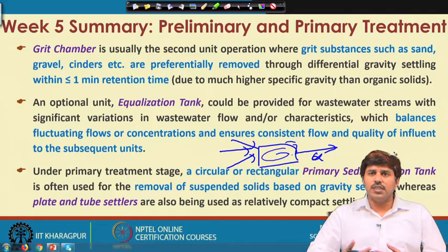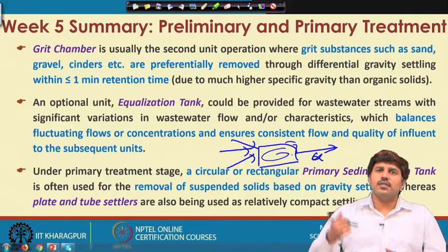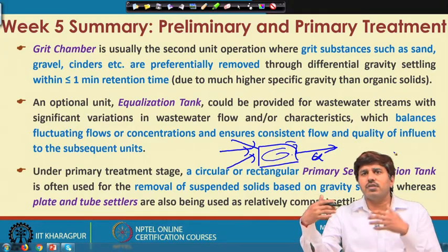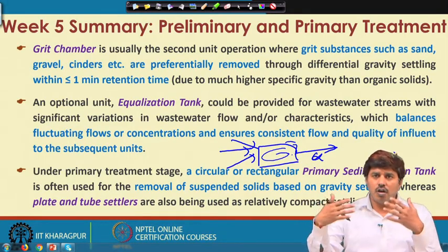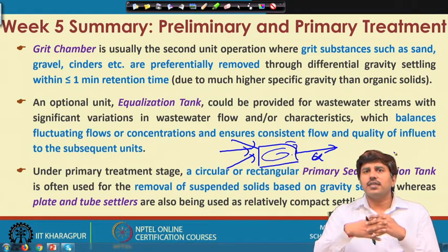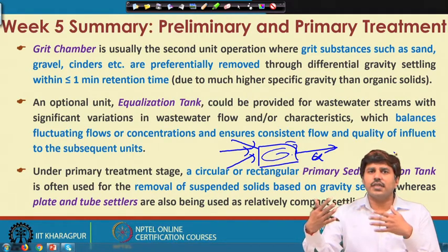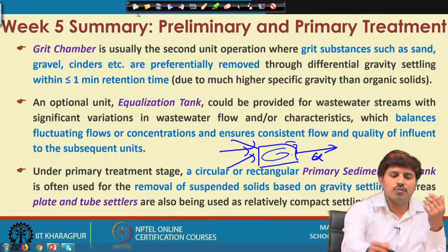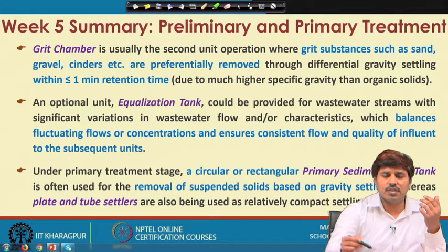Similarly, depending on the need we can go for a skimming tank also, if oil and grease are coming in. So, we can have a skimming tank for the removal of these things, or many times what is done is that oil and grease could also be removed during the primary sedimentation itself.